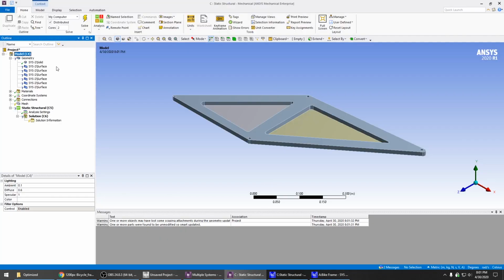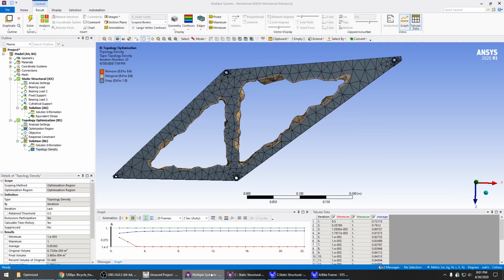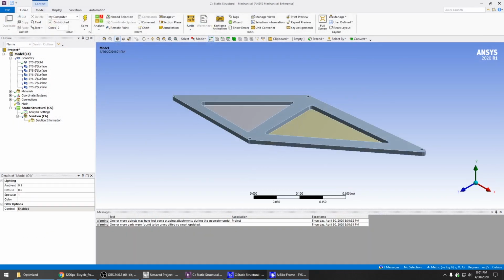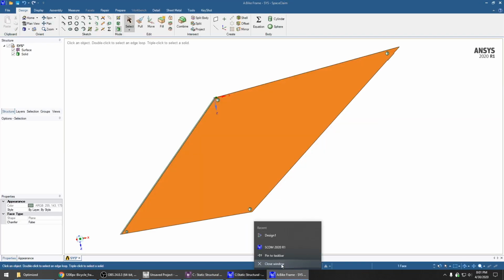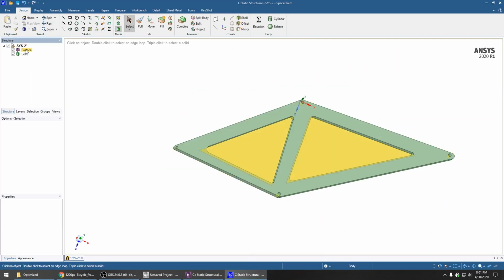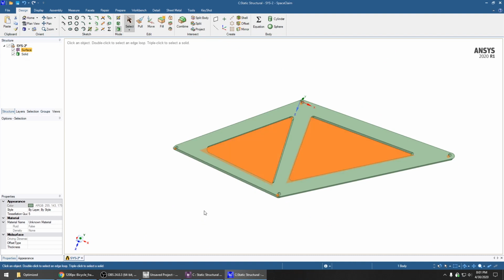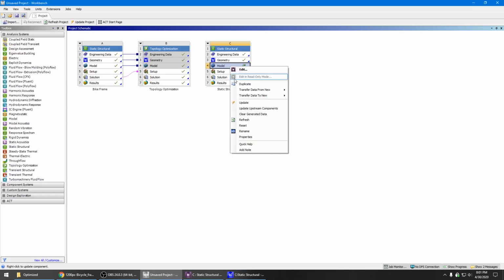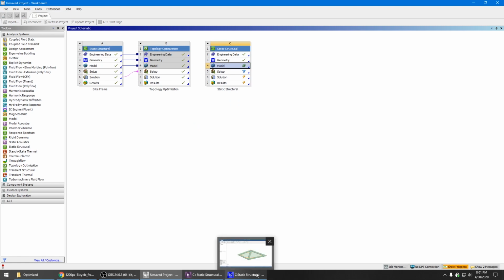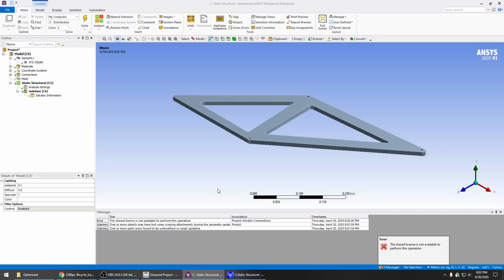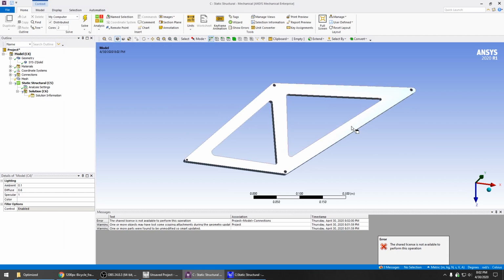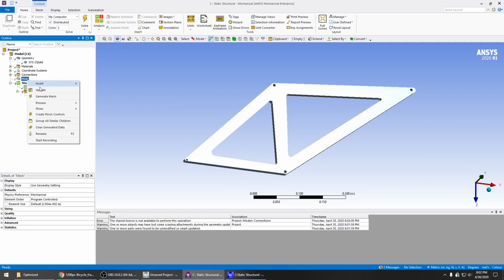Okay, so here is this, and again, I forgot to turn off the surfaces, so we just got to close this. And same with this guy. Just to reduce confusion, go to surface, right click, suppress for physics, and go back to here and update it. There you go. You got a nice thing here, and right click on mesh and generate a mesh. I hit update. I have to press generate mesh.